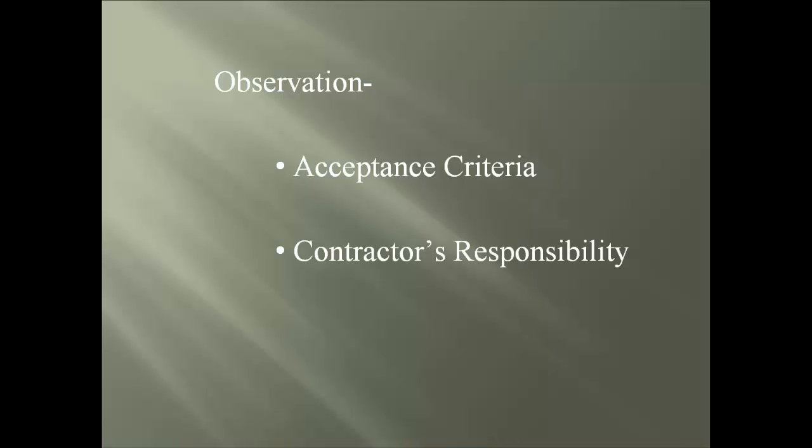Next is the contractor's responsibility, which includes the proper approved WPS, whether pre-qualified or qualified by tests, plus welder qualification, and providing access to the work area with safe conditions. And lastly is the work itself. At any time during welding, a request of electrode melt rate, wire feed rate, or welding current can be compared to the approved WPS, and if the quality of the welder's work is judged to be below the requirements of the specification or code, a requalification of the welder can be requested.